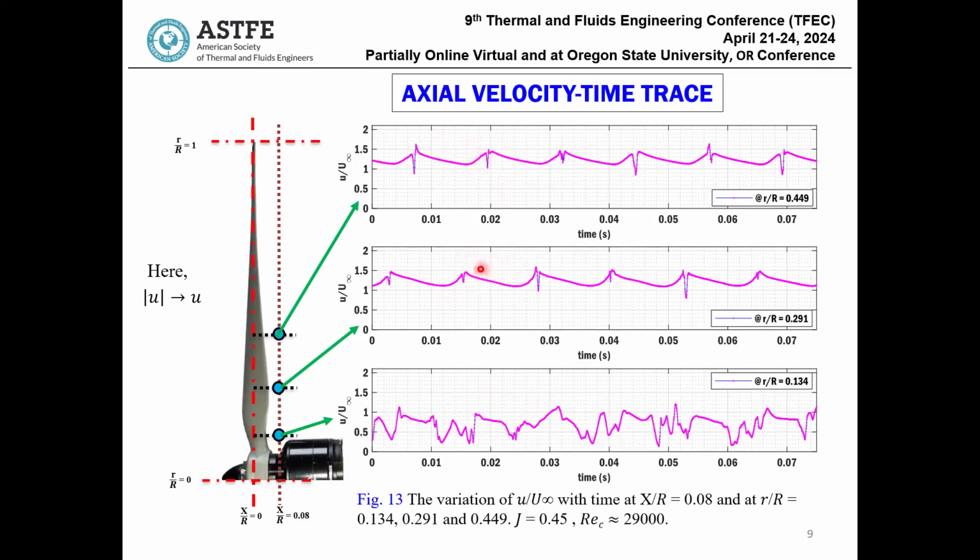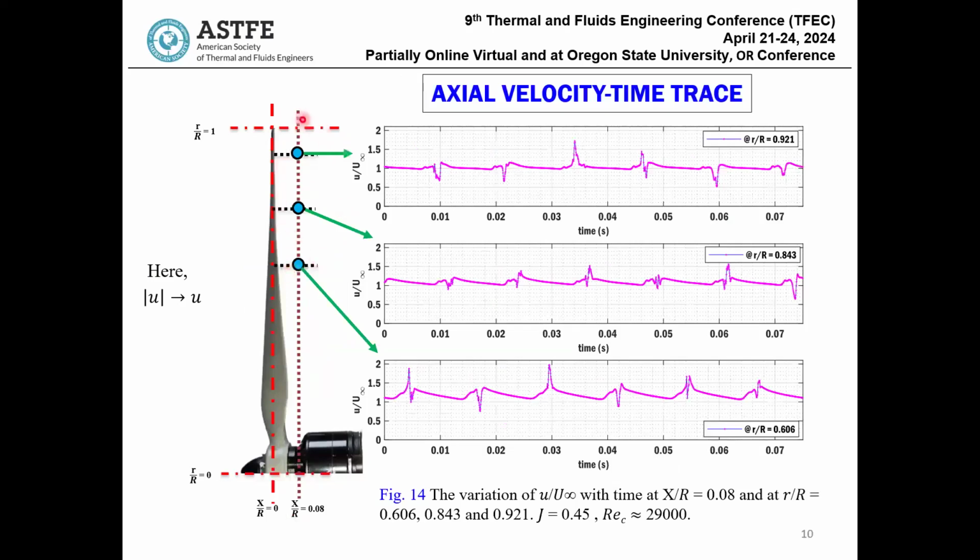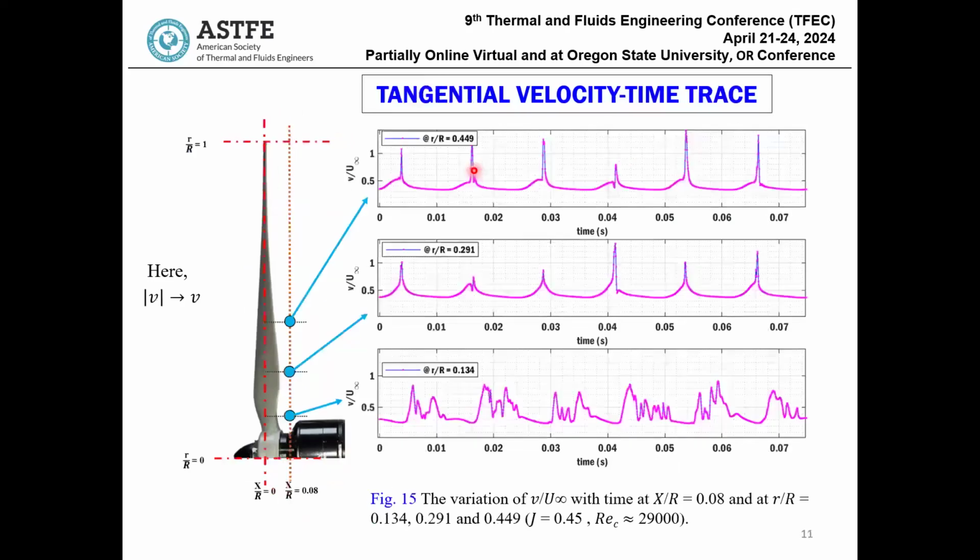In the unsteady laminar region, the velocity has temporal deceleration and acceleration in the near mid-wake region, and the same for the region very near to the plane of rotation. But when you approach the tip for the same plane, you don't see much change, like no acceleration or deceleration in the laminar portion of the wake.